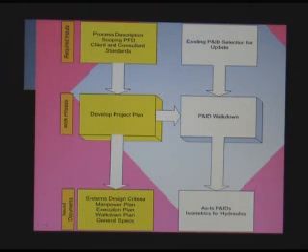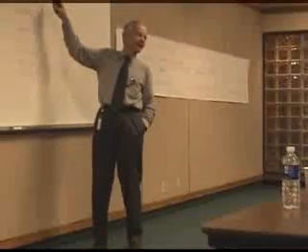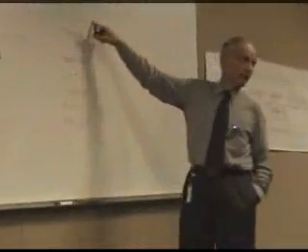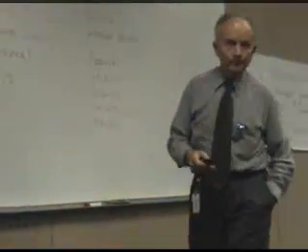So the first step is to select the P&IDs that need to be prepared, or updated, rather, and produce an issue of P&IDs that is an accurate representation of what's out there in the plant. That's the first issue, called as-is P&IDs. Some people call it as-built, but as-built only happens at the end of our project, not at the beginning. We haven't built anything. Somebody else did. So those are as-is. That's an as-is P&ID issue.